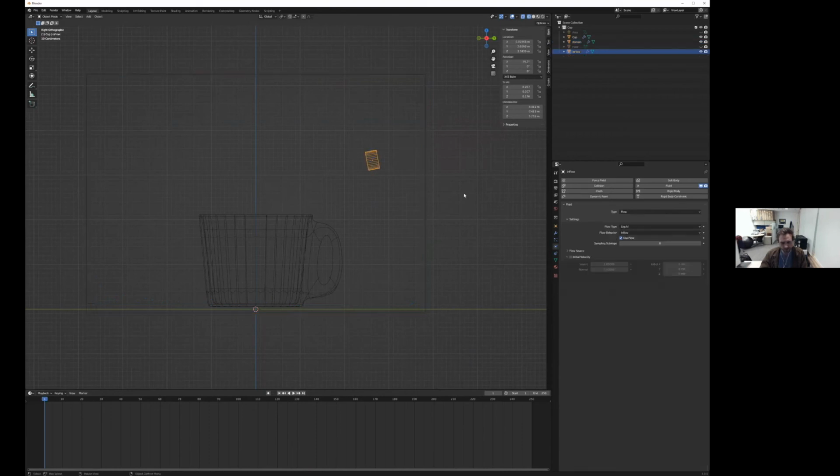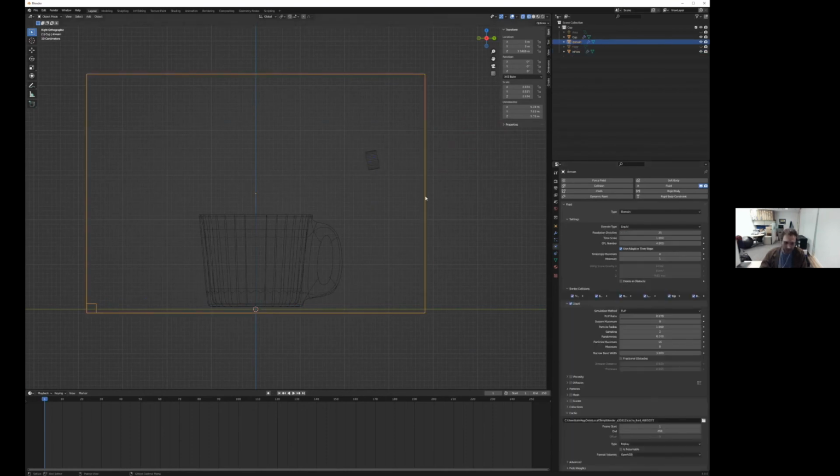So if I click here, I have this initial velocity. So now I can change the velocity of the liquid. If I click this, here I have the options of which direction to go. And so I see this y-axis, I'm on the x looking forward. So let's try y just to experiment. And let's do like 3. So that's 3 meters per second. And so I'm going to hit the domain.